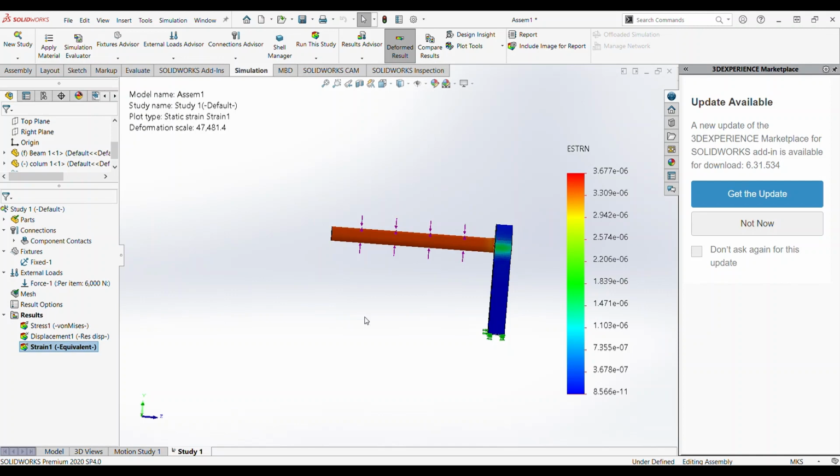Okay, so that's all. And when you think you are finished, you can actually finish here. Other than that, you can make a different study or different simulation, and you will see another tab here if you have a second study, and you can compare two different studies in the same part. When you are finished with your simulation, make a report. Then you should click on this one. So this is the report part.